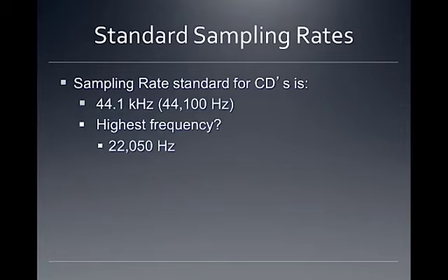It's not going to be converted into digital. Well, that filter slope, how steep the slope is, really is what causes us to have to move into this 44.1 sample rate, because we don't have a perfect, exact cutoff filter.